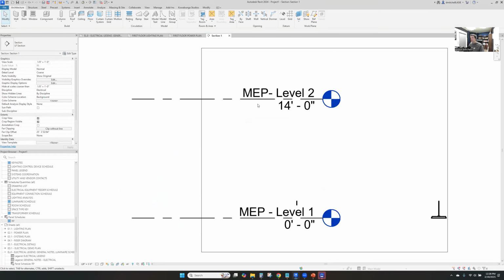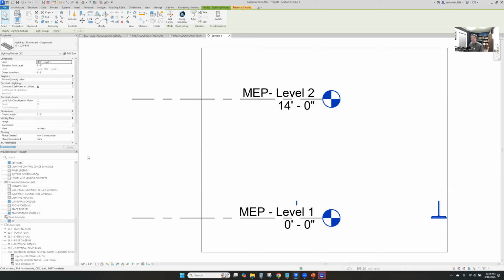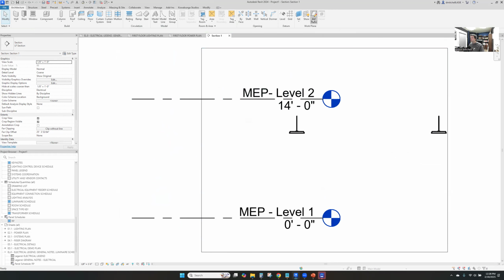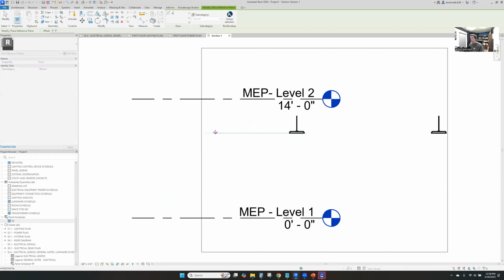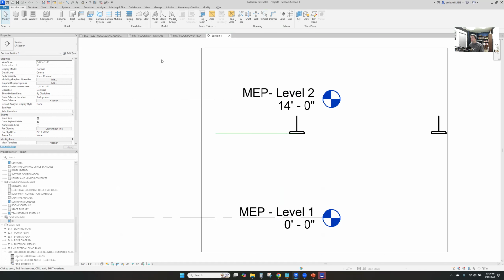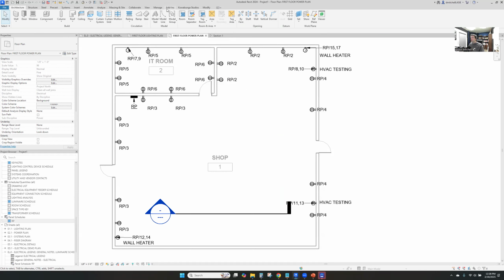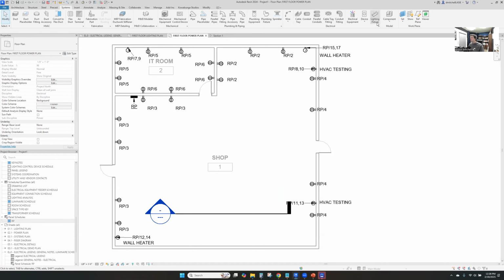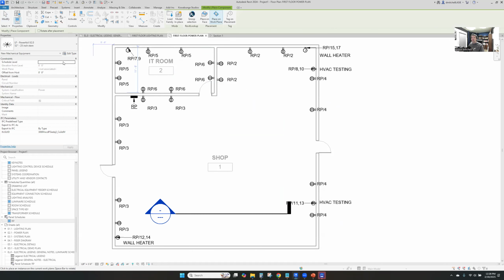Go to view. And we can also select all instances and entire project for light fixtures, these at the proper elevation, 10 feet. And then we can also do a reference plane here at 10 feet. Call this lighting for the reference plane. Go back to our power plan. Go back to our systems, our component, place the component, and then we can put this on a work plane.